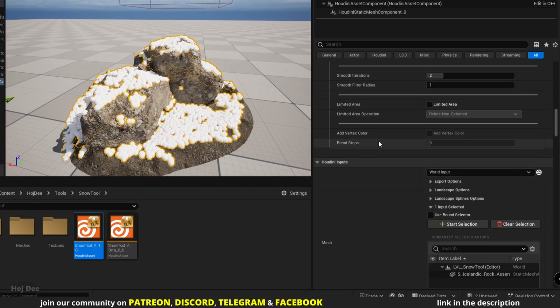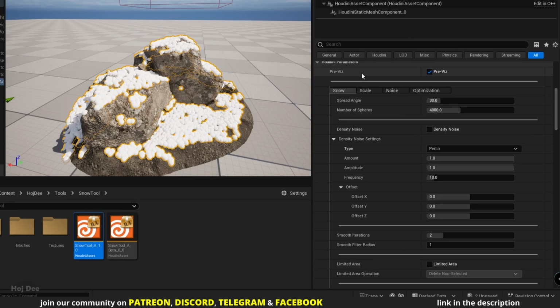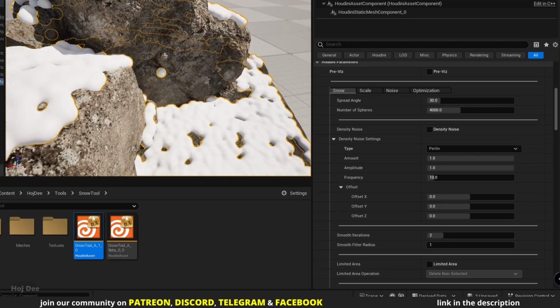Now let's go over the parameters to see how we can edit it. On the very top we have the previous option and it's enabled by default. Previous gives us a faster way to see where the snow will be placed. It's useful when we want to quickly iterate between different parameters to choose the best one. If we disable it, the HDA creates the snow mesh. So let's do that. And here it is. Now we have the snow mesh.